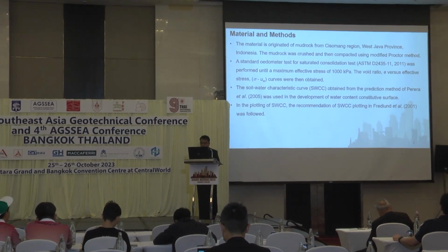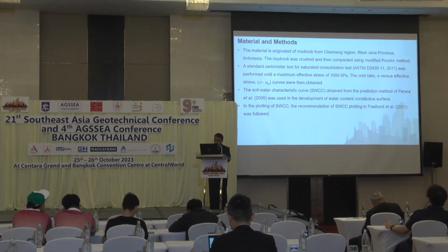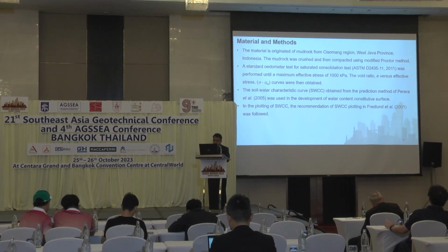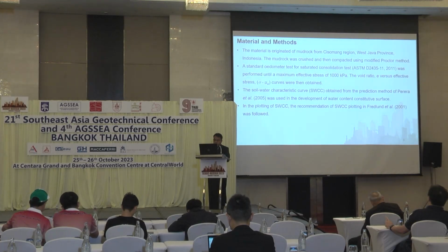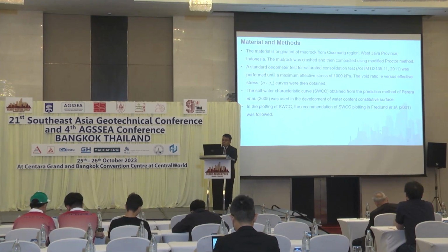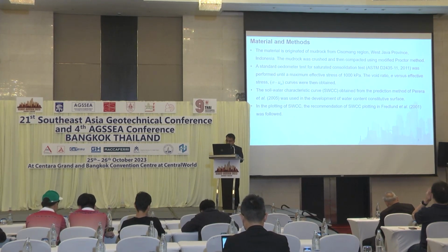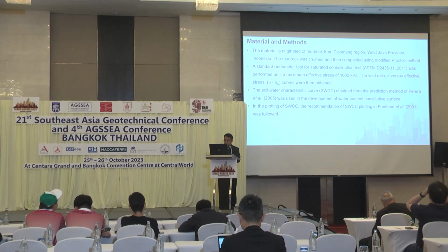The soil water characteristic curve, SWCC, was obtained from the prediction method of Perera et al. 2005 and was used in the development of the water content constitutive surface. In the plotting of SWCC, the recommendation of SWCC plotting in Fredlund et al. 2001 was followed.